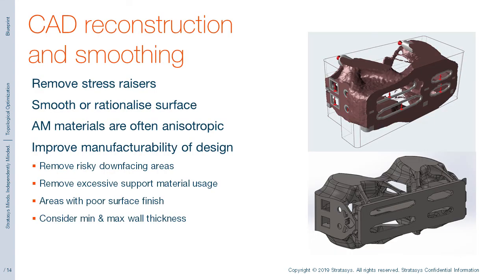If we're able to pass this economic stage gate of the previous slide, then we can carry on with the technical work again. As I mentioned earlier, the results of the topology optimization simulation are often a bit weird. Mostly this is because in order for the iterative top-op simulation to run quickly, the mesh used is very coarse, and with these designs being computer generated, it's understandable that the odd illogical result might occur without a human in the design process. We should consider, can we easily manufacture the shape the top-op simulation has produced, or would it even be practical to use?